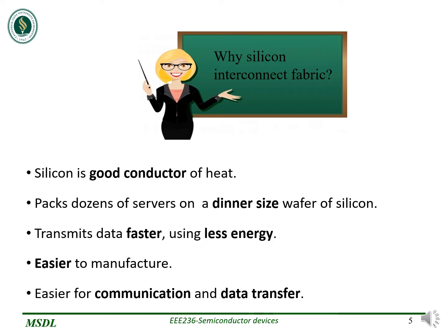It is useful for communicating better as compared to the normal PCB. Due to short wire lengths of less than 500 micrometers, silicon interconnect fabric has excellent signal transfer characteristics with low channel loss and crosstalk, which is used to achieve data rates greater than 10 Gbps per link with fine interconnect pitches. It can achieve 30 times more improvement in data bandwidth and 50 times more reduction in power compared to PCB-style integration.